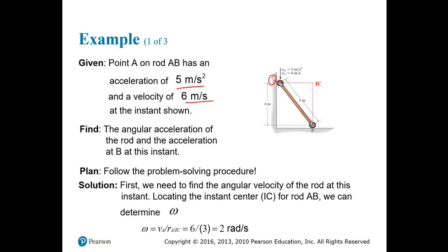So you can see here that the omega of the bar can be easily found because you have the velocity at one point, and if you have that velocity, which is known, and also know the direction of the velocity at B, in this case it could be this or maybe the other side, but it doesn't matter, because you will just draw a line perpendicular to that velocity, which will take you into this.